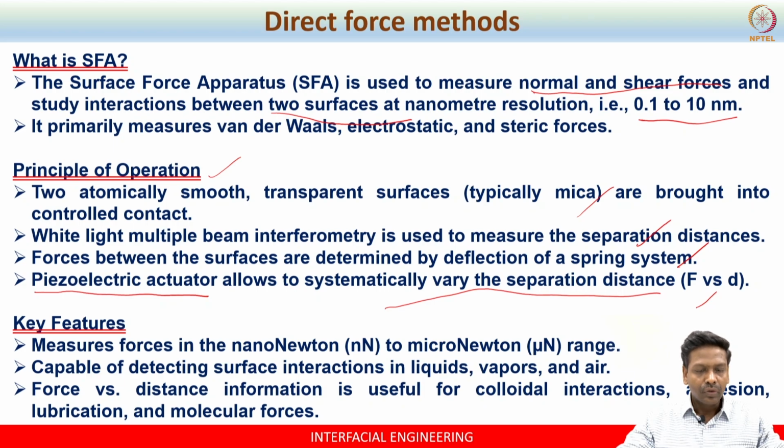Okay, right. So some of the key features of this technique is you can measure the force in the range between at least micronewton range to nanonewton range, right. The force versus distance information is very useful for understanding the colloidal interactions. Okay, and to assess the strength of adhesion in lubrication, and to understand more about the molecular forces.